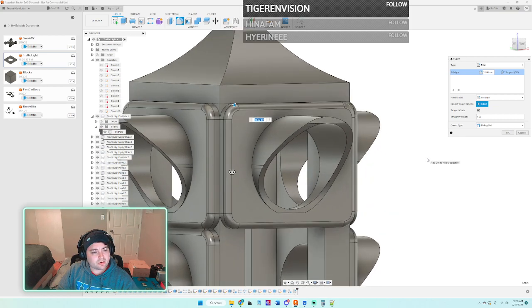What makes it harder to print? Aesthetically, rounded always looks nice. In terms of printing it, would that make it hard to print? Actually, no. It makes it better to print because you're reducing the amount of material that you're using, and there's something called stress lines in PLA. So when you have to do too hard of a turn when you're printing in PLA, it creates something called a stress line, which comes from extruding things in difficult ways. Rounding it actually creates less stress lines when you're printing, so the print becomes slightly stronger, so to speak. The only way to truly get rid of stress lines is like annealing it, but we're not going to do that here.